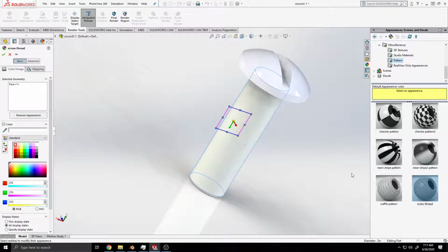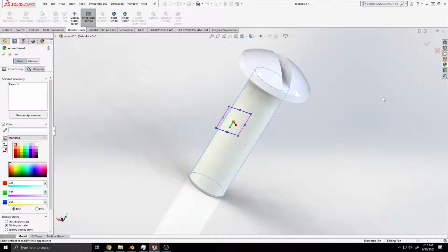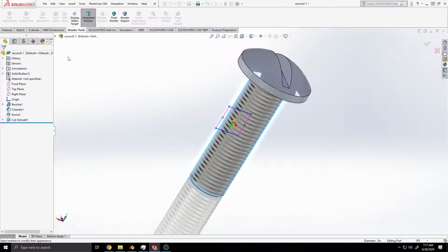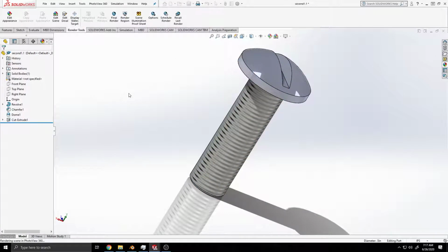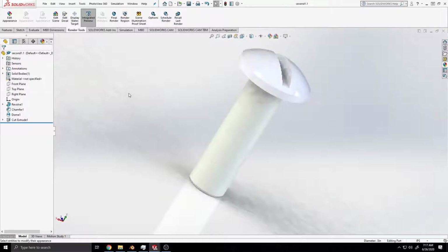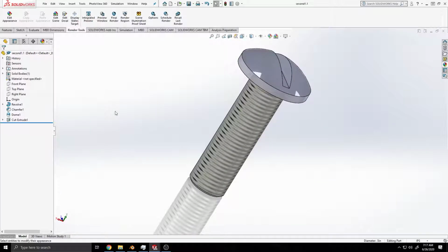Now, take your centerline tool and draw a vertical and horizontal centerline. If you remember, this is very similar to Lab 1B. So it's really a lot of review. Over here, go ahead and draw a circle floating out there. Be sure not to touch this line.